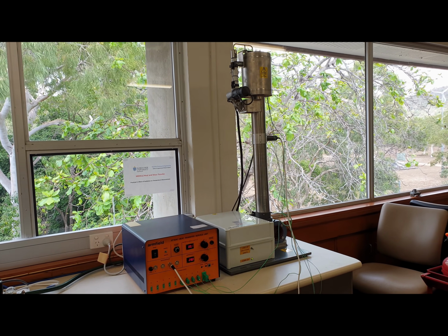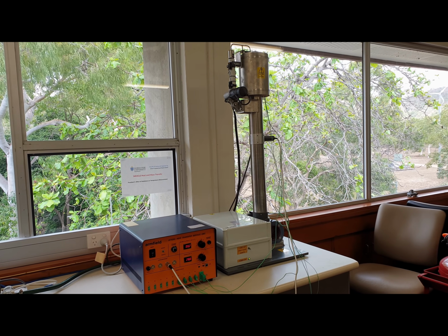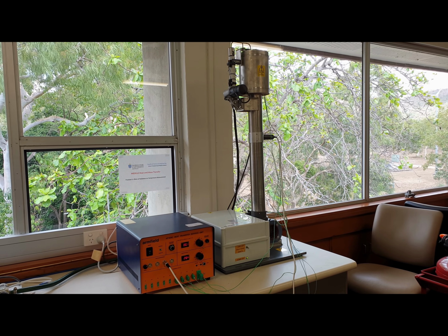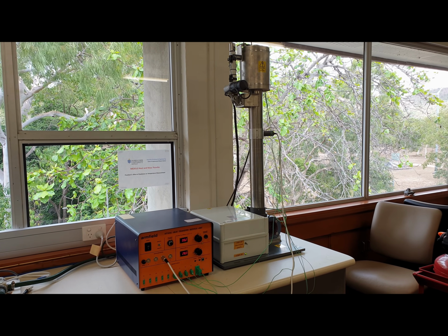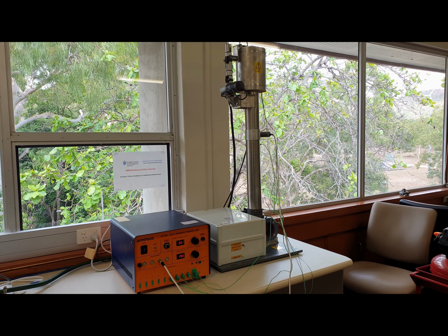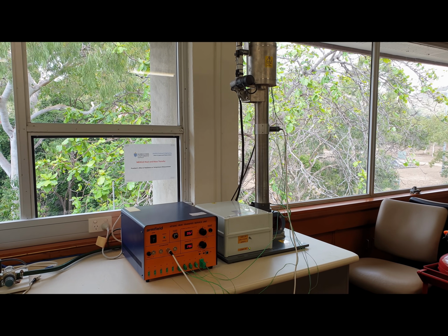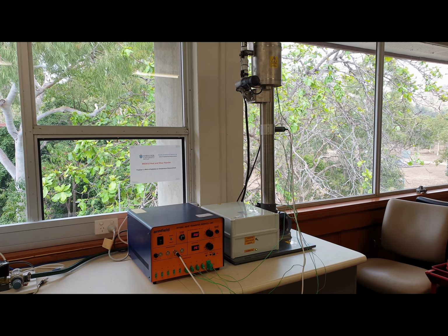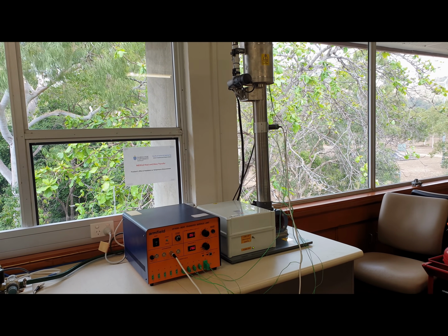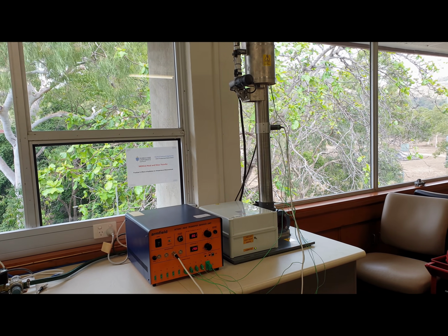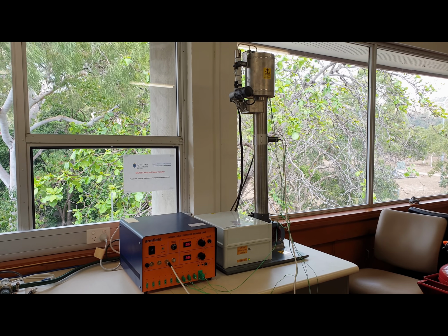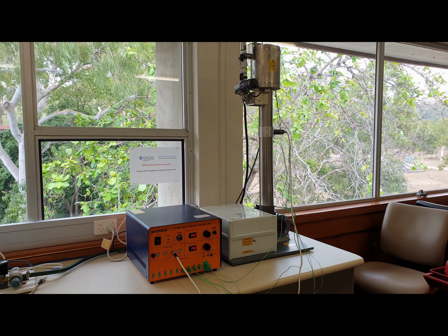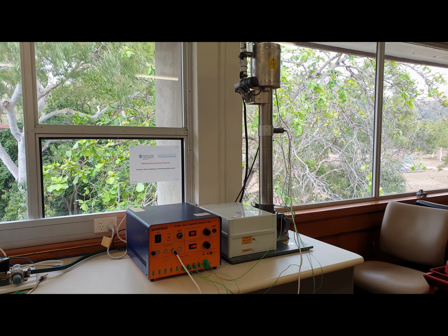Arrangement number 3: no flow, so flow velocity is going to be 0, but I'm going to raise the radiation shield. And arrangement number 4: we are going to have both radiation and forced flow. Basically, we are going to have some velocity, plus the radiation shield is going to be raised and open. We are going to have an open surface between the heated surface and the thermocouples, so we have radiation there.